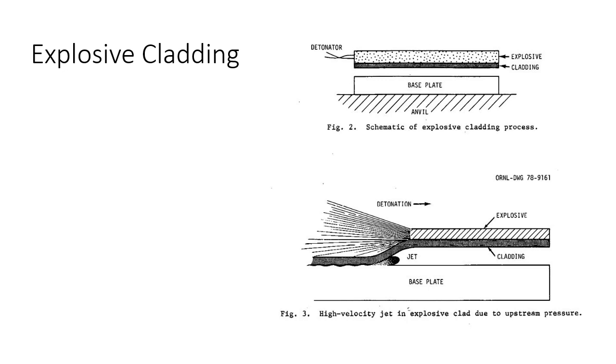Okay, here we've got explosive cladding. I couldn't end on just cladding alone. I needed to talk about explosive cladding. Whether or not you ever run into an explosive clad material, I don't know, but I thought it was pretty cool. I used to deal with some explosively bonded clad material where they'd take stainless steel and aluminum, and they'd use an explosive charge to get the two materials to bond. So here you've got your clad material that you want to be stuck to the base plate, and then they light this thing off, and as it goes, it forces the two materials together.